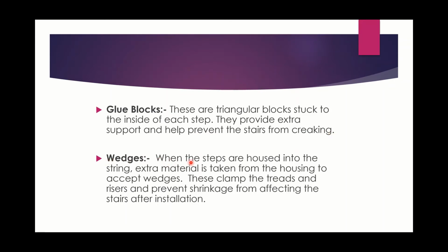Wedges. When the steps are housed into the string, extra material is taken from the housing to accept wedges. These clamp the treads and risers and prevent shrinkage from affecting the stairs after installation. Again, this will all become more clear when we look at some diagrams.